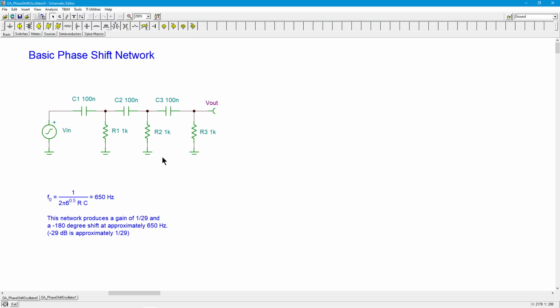If you tried to do a 60-60-60, right, 60 degrees each, and I explain this as an introductory element in the free op amp textbook, right, that you can download, the issue there is you have to make sure that subsequent stages don't excessively load. In other words, the C1 R1 is loaded by C2 R2, C3 R3. And C2 R2 is loaded by C3 R3. So you would actually like these values to be an order of magnitude bigger than these, and these to be an order of magnitude bigger than these. So, you're looking at some pretty big values.